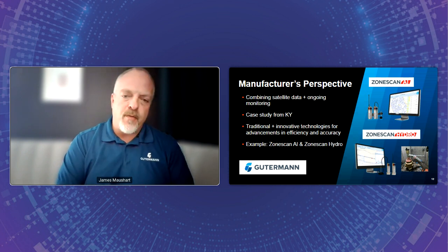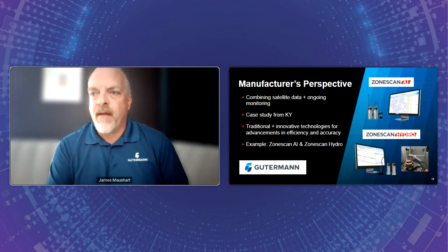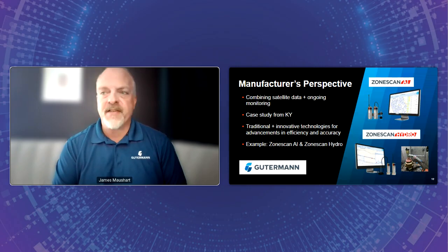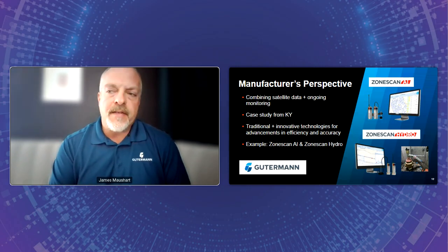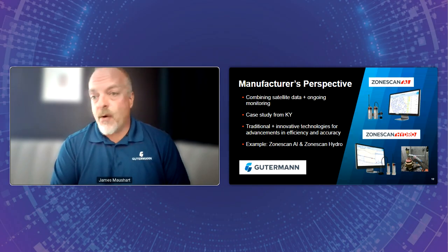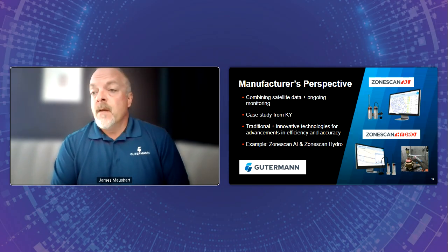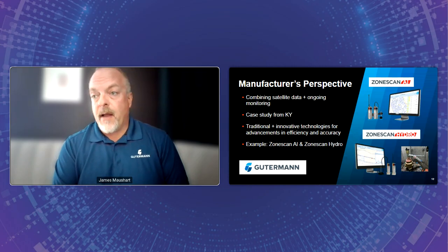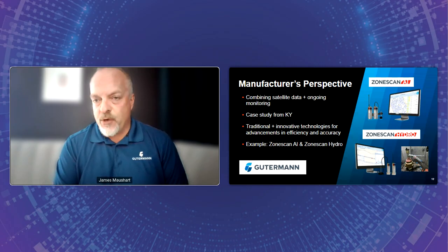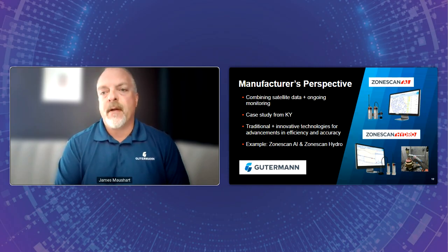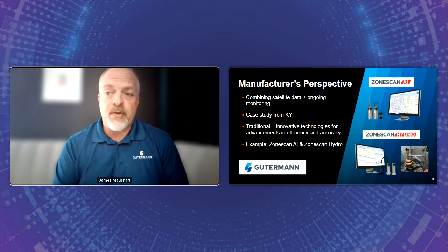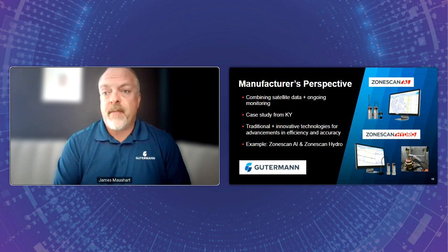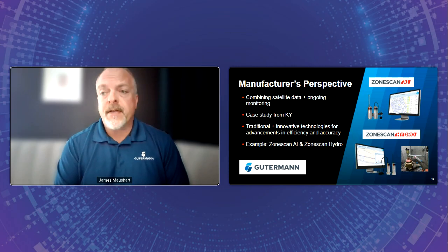So with Guterman, just to coincide with what everyone has been talking about, having a program in general, multifaceted, with more tools for the toolbox, you're going to get a lot more results, proactive versus reactive. The way I've always looked at acoustic leak detection and reporting, there are 3 steps. It doesn't matter where you are in the world, if you follow these 3 steps, you're going to get the results you're looking for. Survey, correlate, pinpoint. Survey could be with the satellite, it could be with loggers, it could be manually, it could be several different ways.